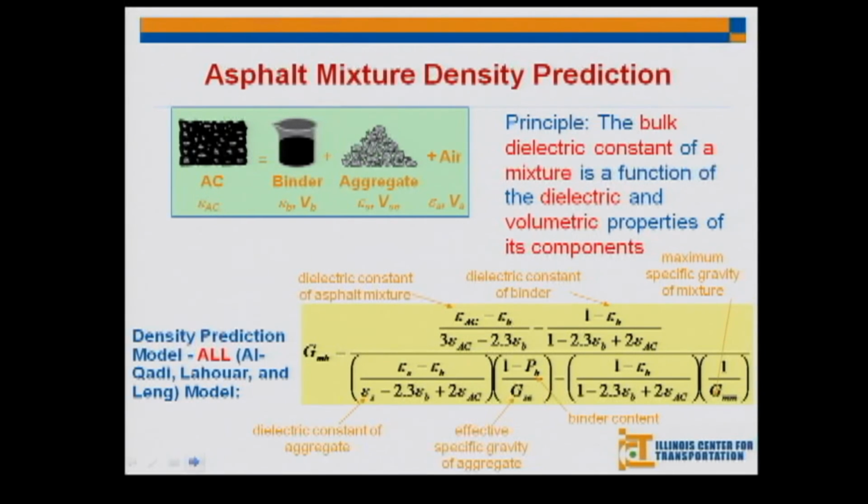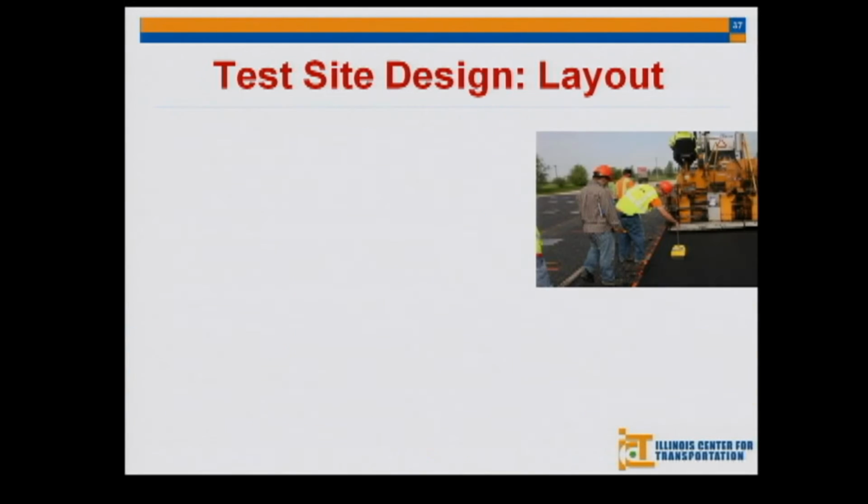Of all this, the only thing that we really don't know, in my opinion here, is the dielectric constant of the stone. If we can get a good handle of this, then we'll be able to measure the dielectric constant and then the density on the go.